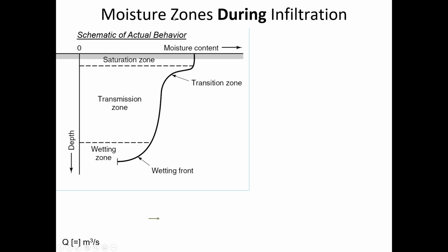So during a storm, the water gets downward through the soil, and of course this is just thinking maybe in one dimension, because what we know from that previous video is it's also moving outward. But let's assume that it's raining over a large area, and so it makes sense for us to think one-dimensionally, because if we have a certain column of soil that we're looking at and it's raining in a wide area, then any particular element of soil that we're looking at, the water's just going to be going downward.